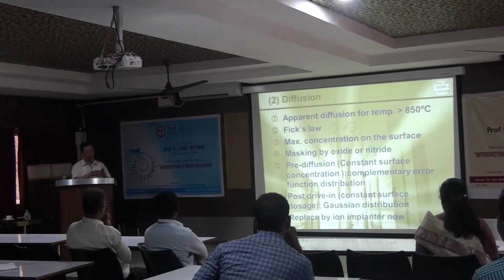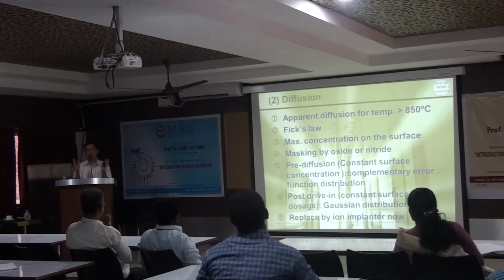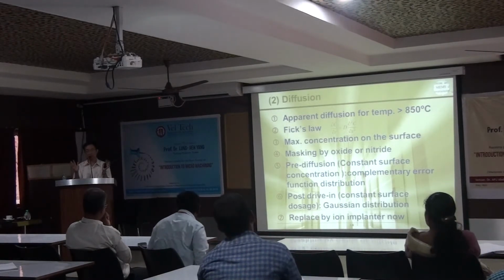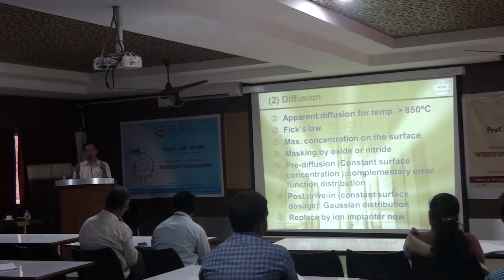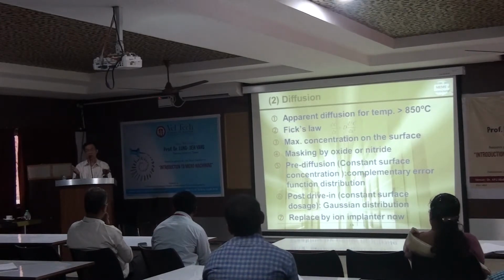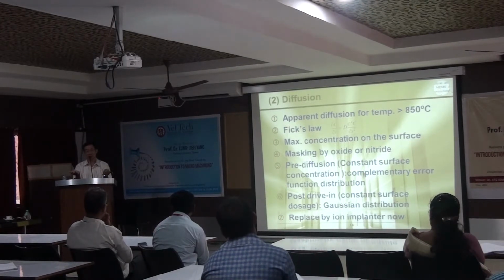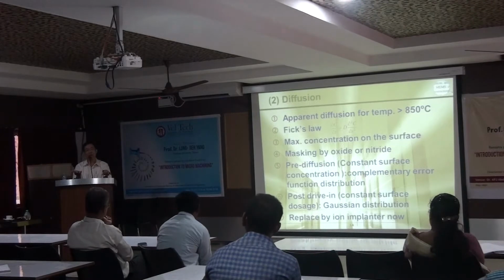But after you release it for a long time, you will find it saturates. Even if you extend the time of diffusion, no more dopant will go into the surface. Impossible, because there is too much. It's something like a traffic jam, very similar, right? A lot of cars going onto the highway, nobody can move anymore.